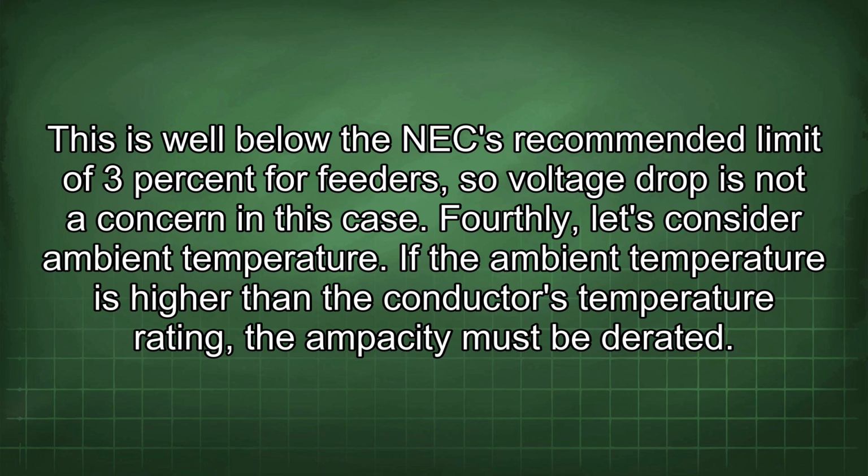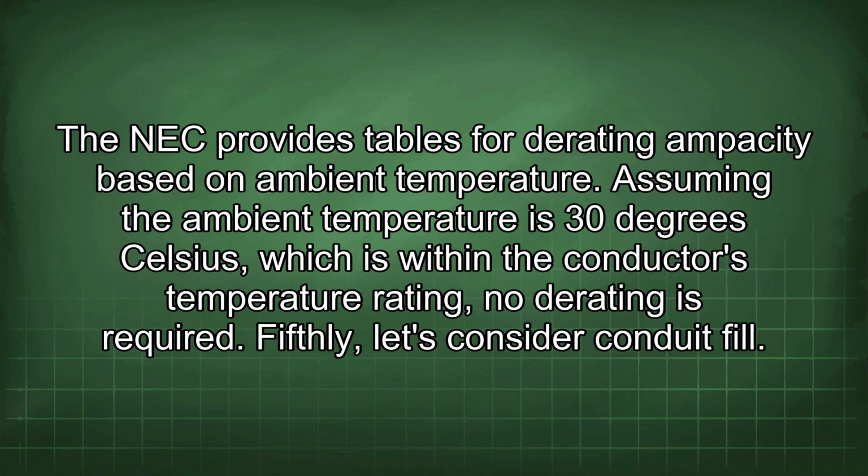so voltage drop is not a concern in this case. Fourthly, let's consider ambient temperature. If the ambient temperature is higher than the conductor's temperature rating, the ampacity must be derated. The NEC provides tables for derating ampacity based on ambient temperature. Assuming the ambient temperature is 30 degrees Celsius, which is within the conductor's temperature rating, no derating is required.